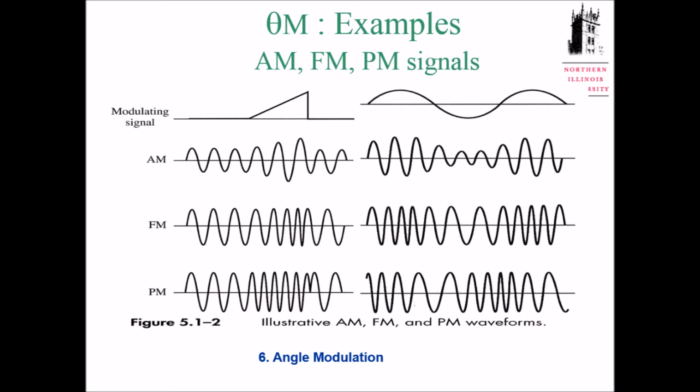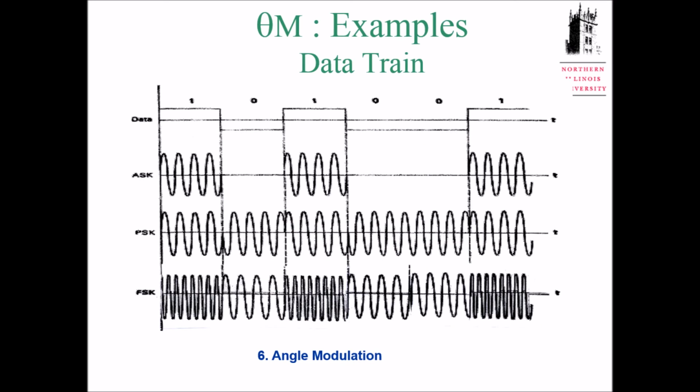But for FM, the carrier phase is continuous. For PM, this one is very close to double sideband suppressed carrier, right? Phase reversal. So when your signal dramatically passes zero in PM, there will be a 180 degree phase change. Similar to this one.